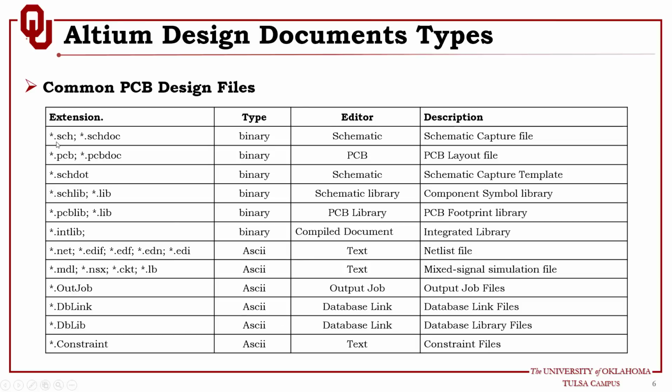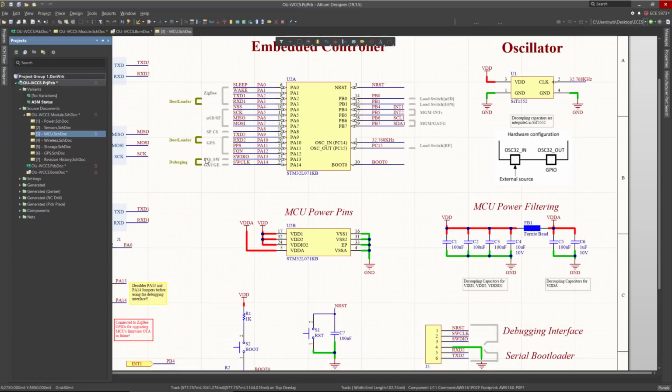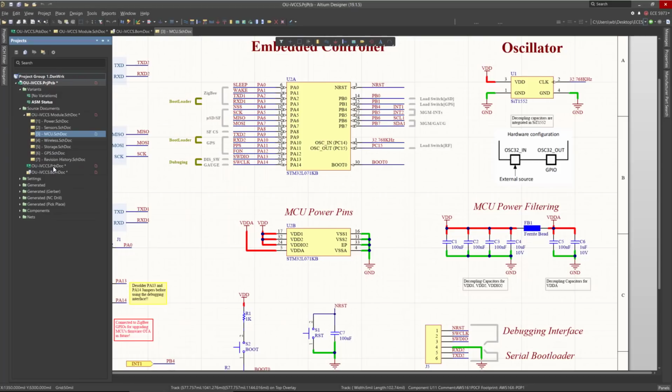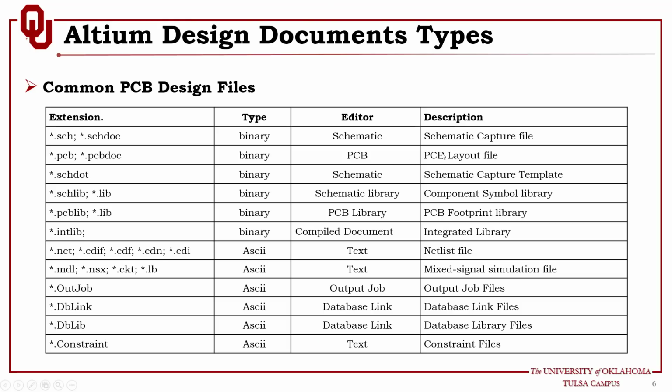So you have the schematic and schematic doc documents. Here we have schematic doc. As we can see, these are all schematic documents, and these are schematic capture files. PCB doc is the PCB layout file. If we come here, these are PCB documents, PCB layout files, and all these are binary files.